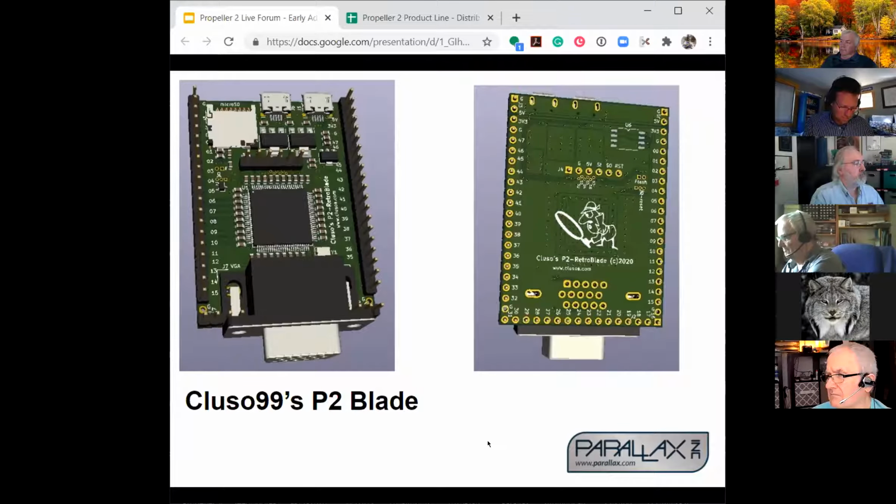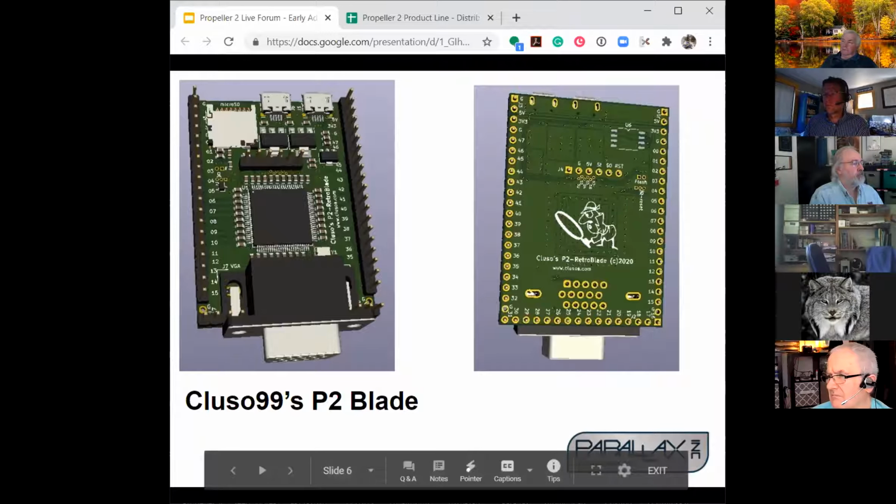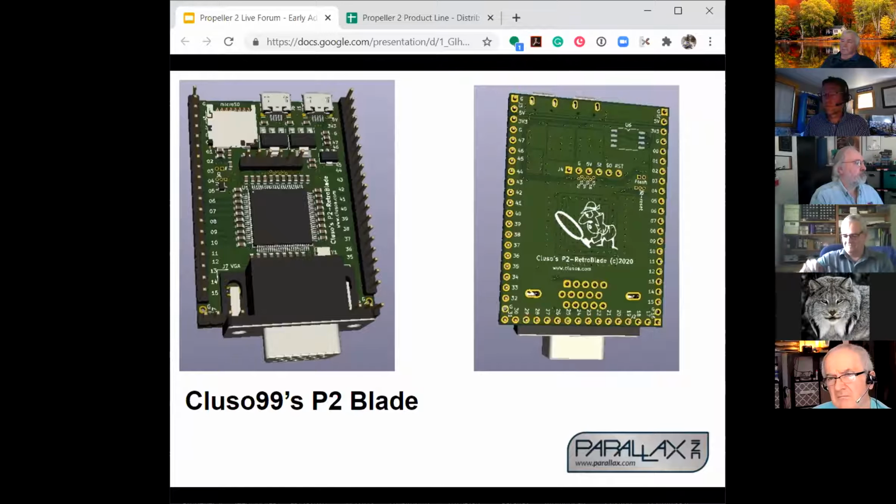If I started, say, 6 pins with the same sine wave, is there any way with the direction registers to shut 5 off till they're needed? Technically, yes. That may be the way I need to go. You start them all at the same time, and then turn off the DIR bit so that you put the smart pin into reset. Once you put it back into a driven mode, the smart pin would reactivate. I'll have to try that.